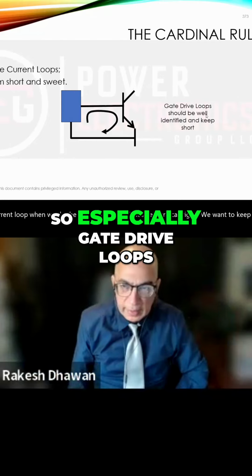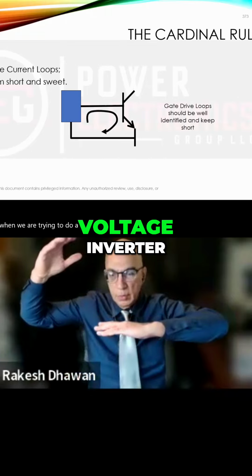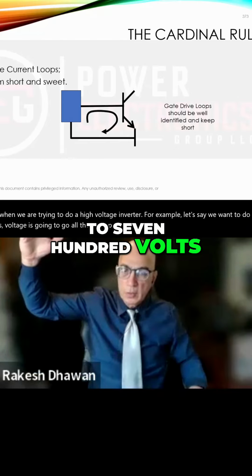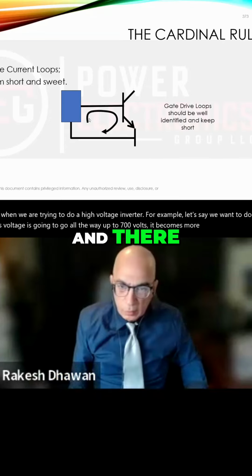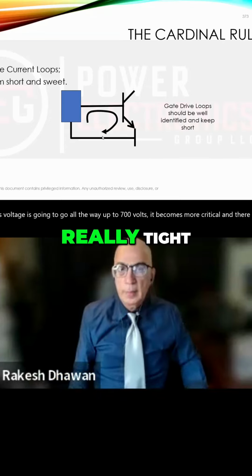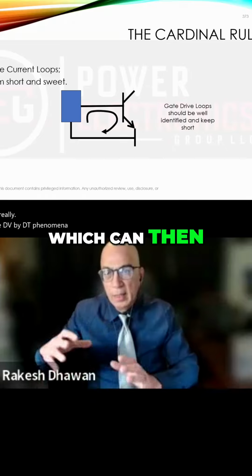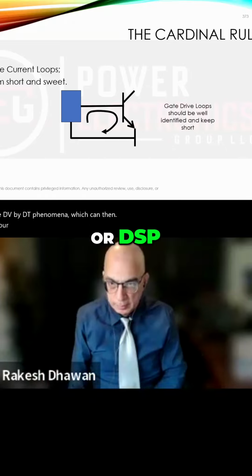Especially gate drive loops, when we are trying to do a high voltage inverter, for example, let's say we want to do a 460 volt inverter where the bus voltage is going to go all the way up to 700 volts, it becomes more critical. And there, your gate drive circuits have to be really tight so that you don't have dV/dt phenomena, which can then cause a lot of noise into your microcontroller or DSP.